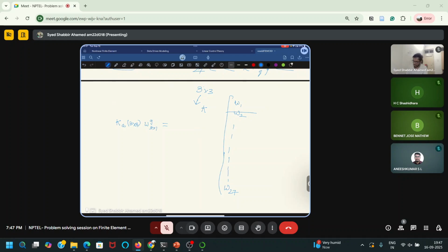That is what static condensation does. And similarly, Q also we have to remove those rows which coincide with the nodes which have zero displacement. So if I solve this 3 cross 3 system, I'll get the deflection at the center of my plate. That is how we can solve it.